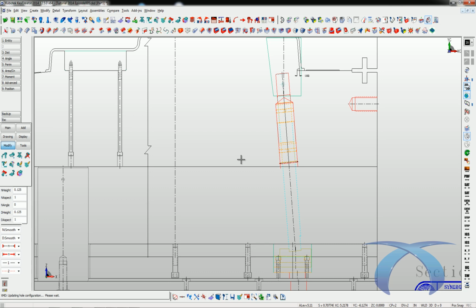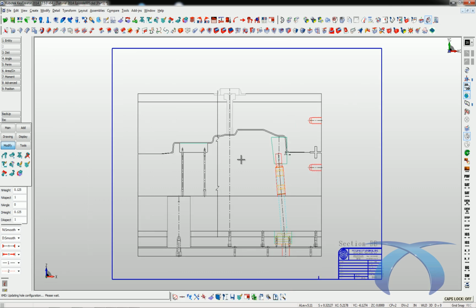Okay. So the last thing I want to do is we do want to finalize this lifter. Right now the lifter is kind of blocked in for us. It's given us some options on how we do it, depending on how you work in your company. You can take that lifter block and send it to whoever does your modeling. If you have somebody different that models all your parting line and all your lifters and slides and inserts and whatnot, we can send that blocked in lifter and say, here, this is what we want for the lifter, go with it. And then they'll send you the lifter, and you'll use the swap in feature that you've seen in previous tutorials for swapping in the solids. You'll swap it in and it'll be all up to date. If there's any changes in sizes that the modeler made, your material list gets updated automatically. Or we can model it directly in, which is something that we haven't really touched base on.